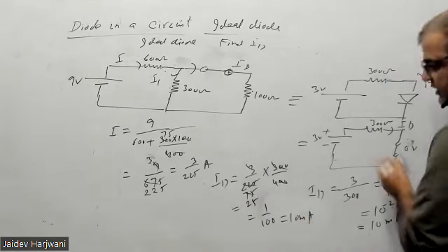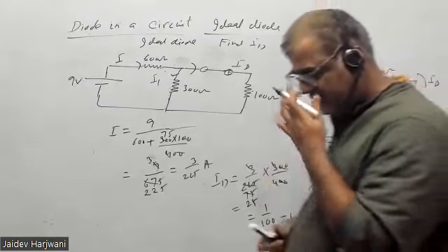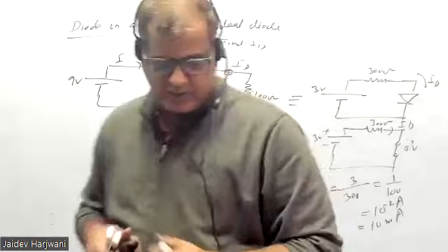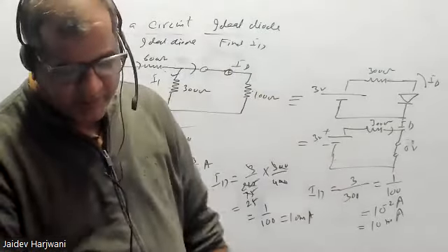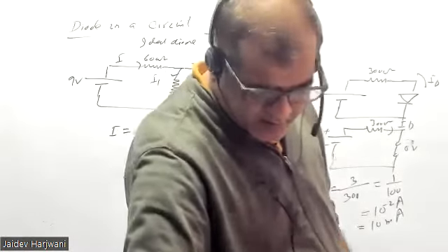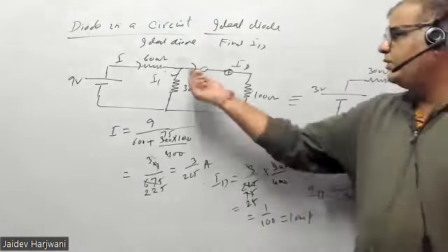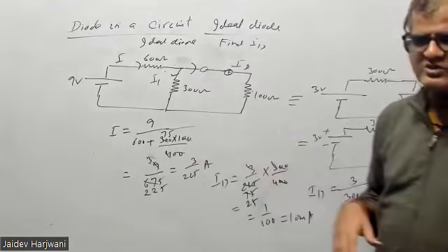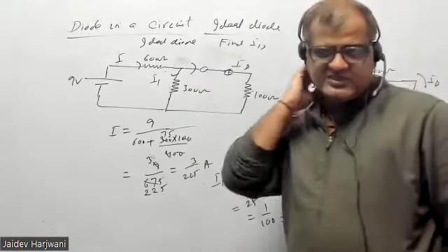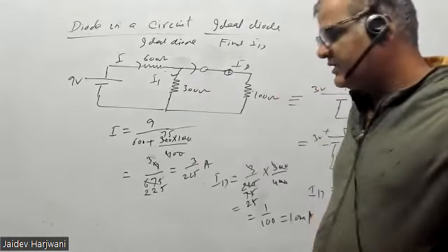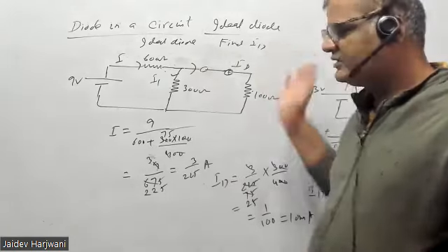10 milliampere, the same is coming. So either you apply the Thevenin equivalent or not, but I suggest you always apply the Thevenin equivalent wherever possible, as it will tell you clearly. This is a simple circuit, so you know only this diode is forward biased. But if there is more than one source, then you first have to judge whether it is forward bias or reverse bias. Only then can we decide what is happening.